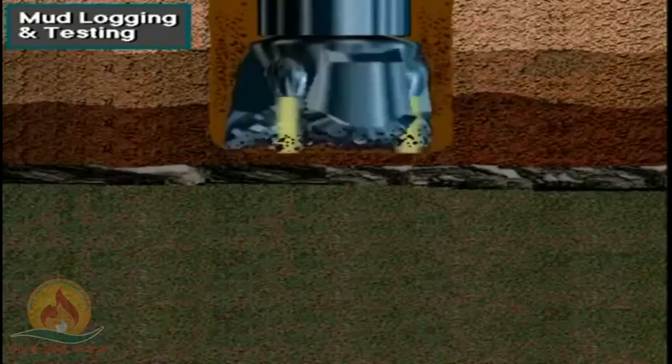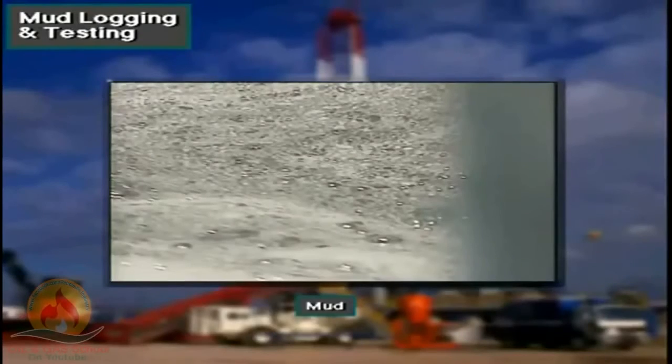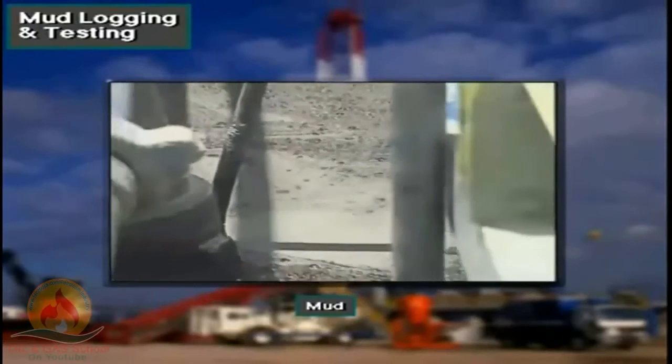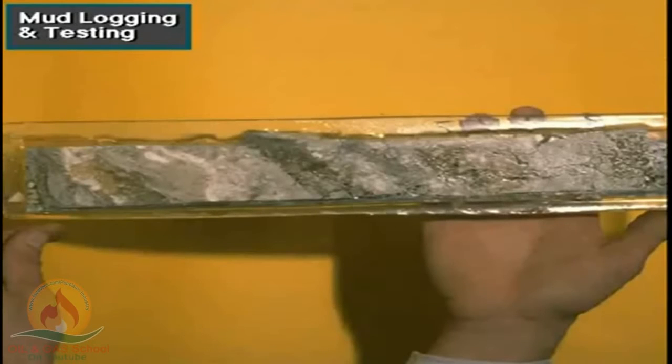As the bit drills, drilling mud lifts cuttings up the hole. The drilling mud also carries traces of any hydrocarbons and other substances the hole may have penetrated. Therefore, catching and analyzing the mud in the cuttings that come to the surface can tell the well owner and geologist a great deal about what's going on downhole as the bit drills. Analyzing the drilling fluid is called mud logging.